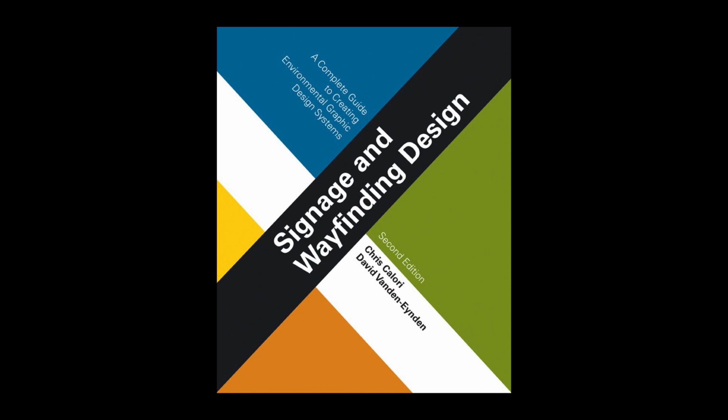Installation and cleanup indicates how the fabricator is to install the signs and clean up after installation, such as coordinating sign installation locations with other trades or parties, installing signs level and plumb, restoring any adjacent areas damaged by sign installation, removal of fingerprints and dirt from installed signs, and the like.